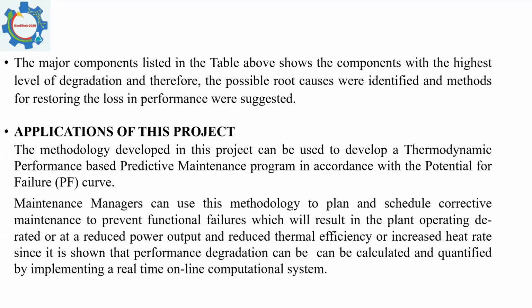And similarly, you may end up with an actual efficiency based on actual plant parameters that is better than design, and that is totally impossible. So these things sometimes point to errors in the instrumentation, which you have to rationalize and determine how to get around to be able to calculate the real actual performance. So this is one of the things that you have with plant instrumentation, the accuracy, and also the fact that sometimes they go out of calibration.